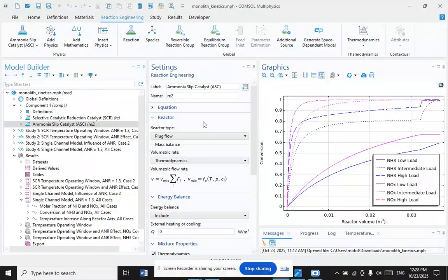Some newer diesel engines, namely those installed in combination vehicles, can also perform what is called a parked regeneration, where the engine increases RPM to around 1400 while parked to increase the temperature of the exhaust.